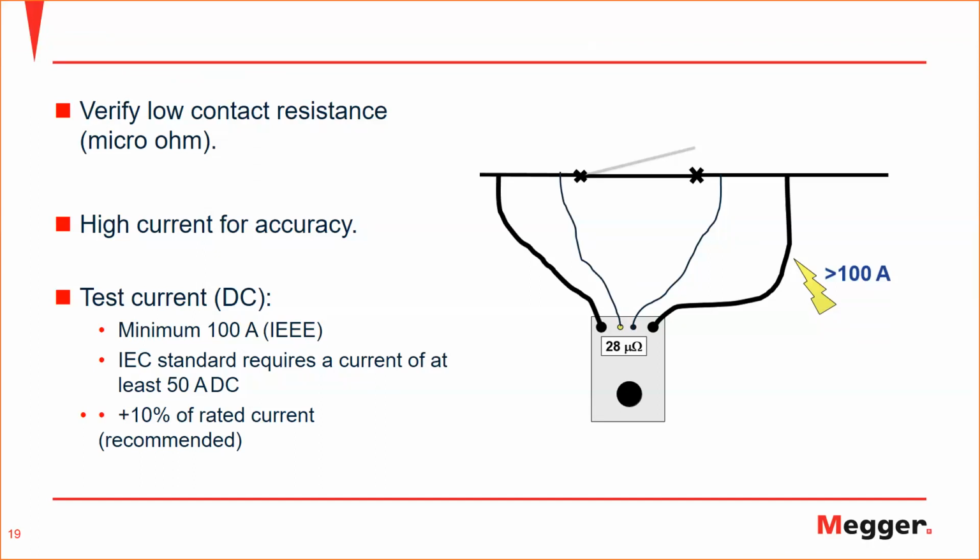I measure the contact resistance while the breaker is operating, during that very short window where your breaker is only being connected through your arcing contacts. It is a very important test for these arcing contacts, and it's not done alone. There is another test usually done in conjunction with it or in parallel with it, which is the motion test. We will talk about that later on though.